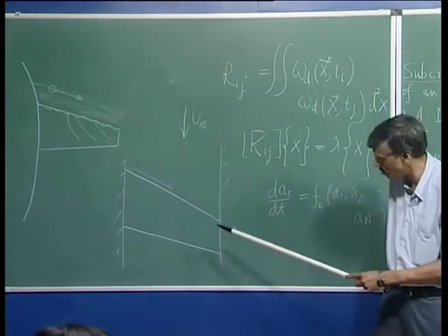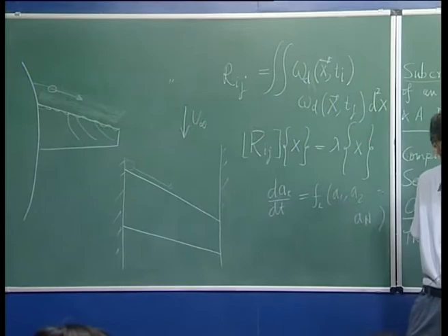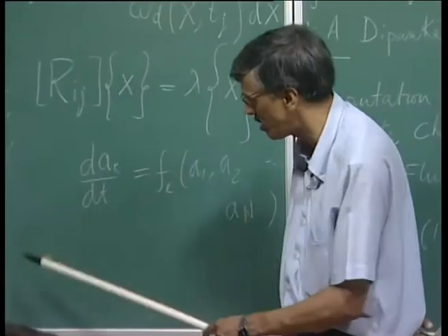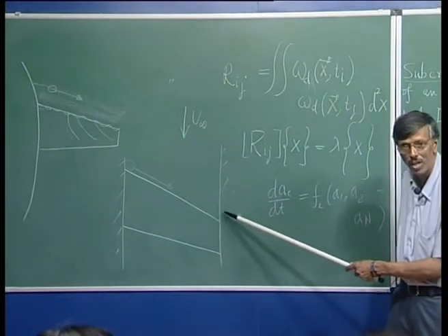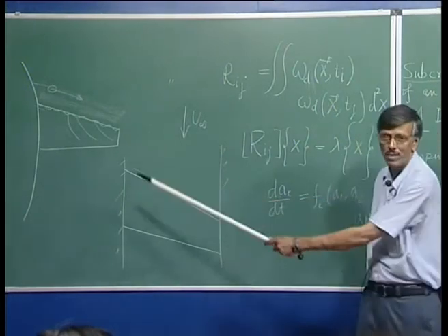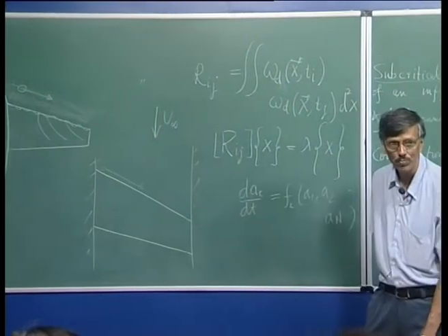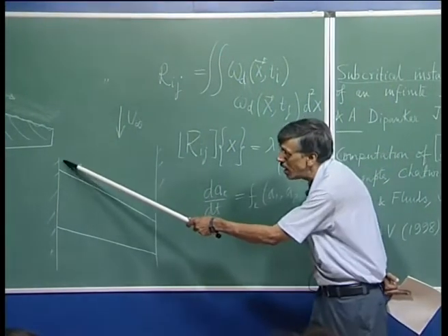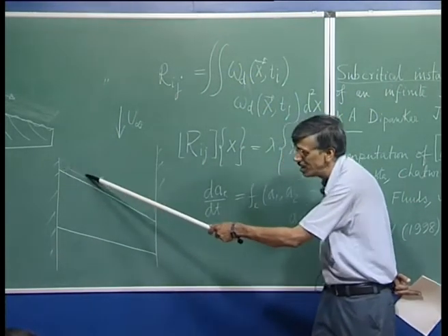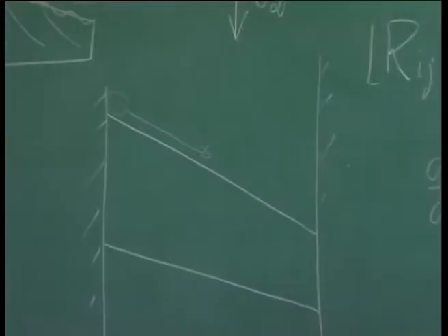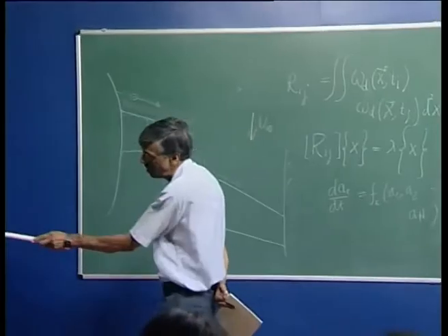So, that is why these experiments are very trustworthy and reliable, simply because the vortical structure that is getting created on the other wall will not propagate against the sweep. Instead, the vortical structure created here will naturally move along. So, that is your attachment line plane, the way we have shown here.